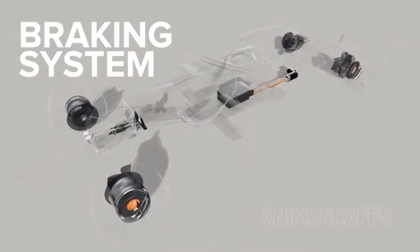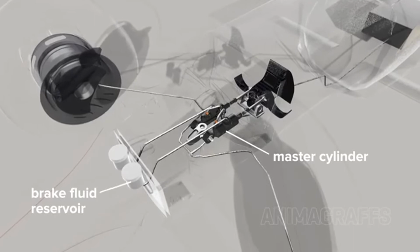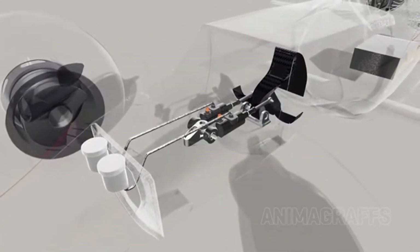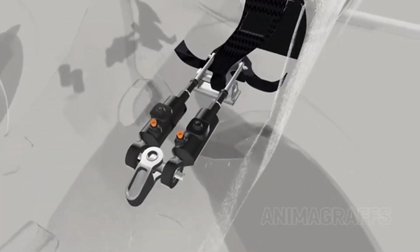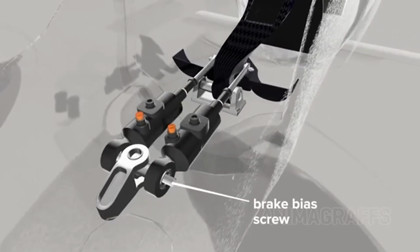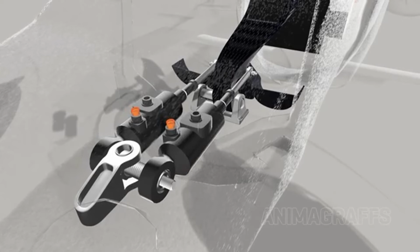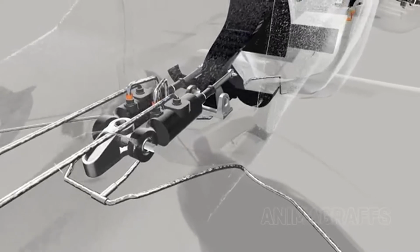Braking system. A master cylinder and reservoir controls and stores hydraulic fluid for braking. F1 cars have two master cylinders and accompanying reservoirs for front and rear brakes respectively. The cylinders are mounted to the brake pedal on one end and a threaded brake bias screw on the other. This bias screw is electronically controlled and can be adjusted on the fly as directed by the driver. The screw position allows different pressure to the front or rear brakes.